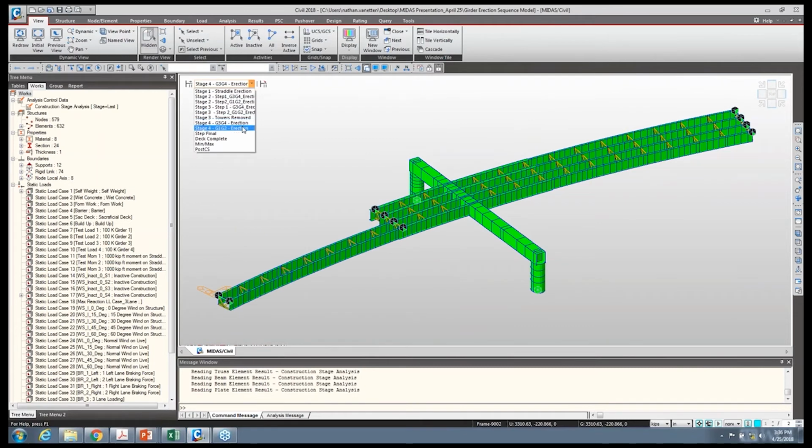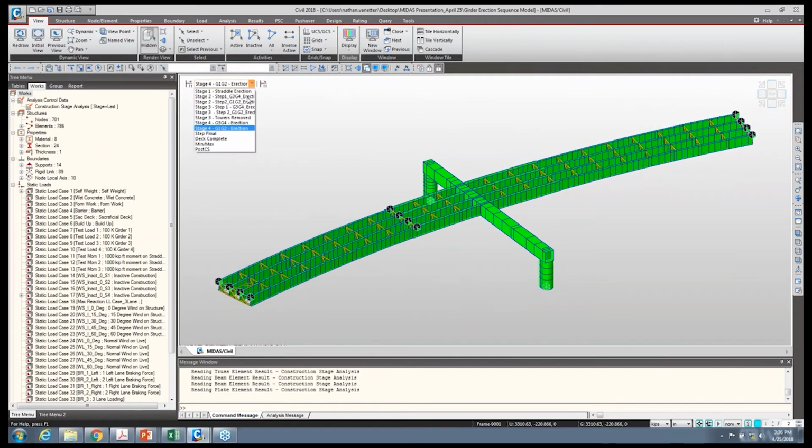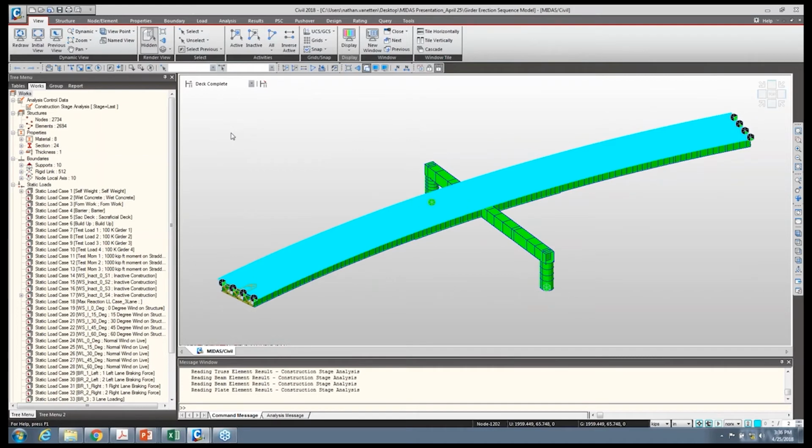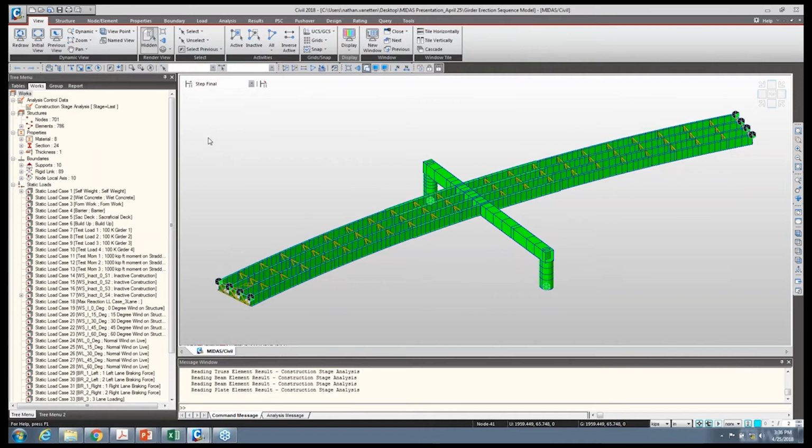So as you see here in this first section, I'm activating the groups of tall column, short column, which is the left and right due to super elevation. My first little bits of girder segment, which were the first segments that are bolted on for the first erection, and then the straddle pier. And then activating boundaries. And at this time, I'm not applying wind, although it can be easily. I'm applying self-weight.